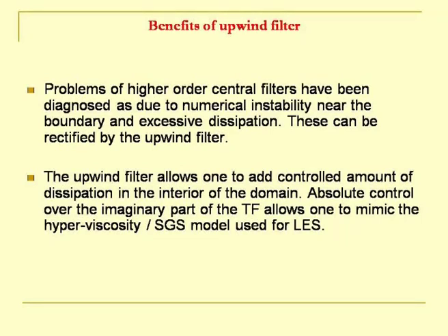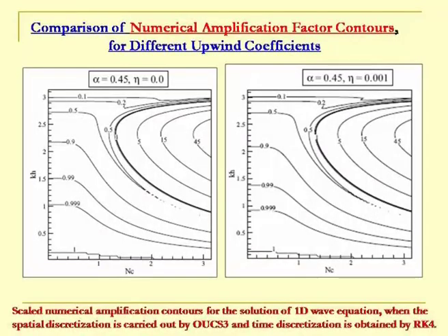Okay. So these subgrid scale models are related to that part of the flow which you are not resolving because of your grid size. Not being able to resolve that scale is equivalent to having some extra stress, and this is what is attempted in subgrid scale stress models. It is a fertile area of research, but let us not worry too much about it. Let us see what we can do if we look at a central filter versus an upwind filter on the right.